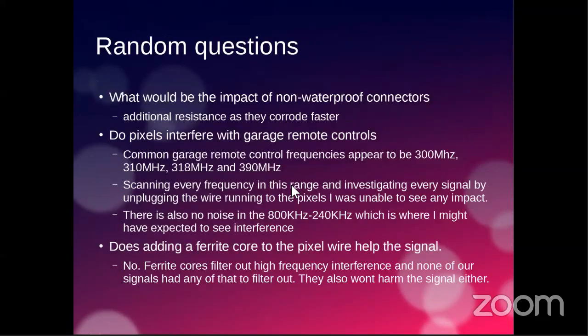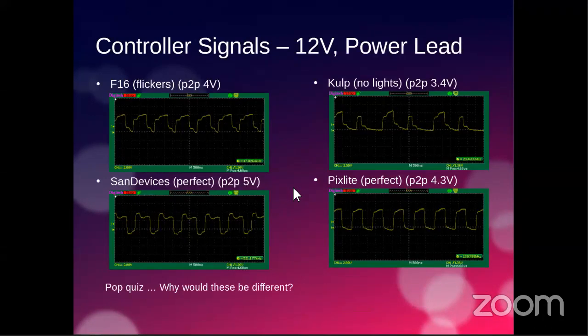Sorry if this is a dumb question, but if 30 ohms works better in a Falcon, why does it come with 100 ohm? It's a good question. I think Dave was trying to be conservative and worried that someone might accidentally connect the power to the data wire, and having an additional resistor in there would provide some additional protection for the board. But it does degrade the signal properties, as you see.